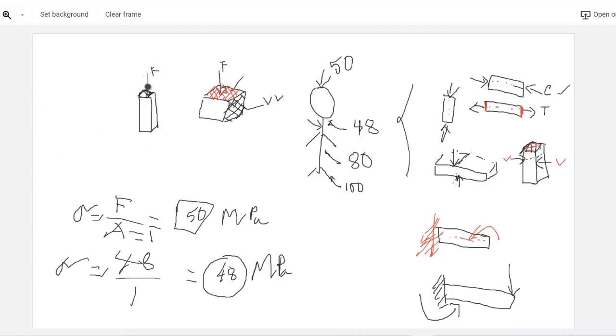Perpendicular, or axially. Yes. So this is axially. So this is perpendicular with respect to the cross section. To add more, you can say this is axially in compression. So the failure might happen axially due to the compression force. While it compresses, you know it will break somewhere, right? Yes, sir. You have already seen this in the compression test of a cylinder. Now this is one kind of failure, you understand.